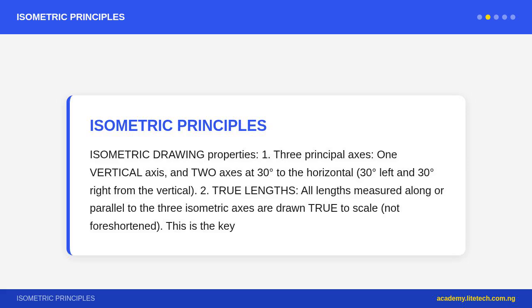Step blocks. Many WAEC questions show a rectangular block with a notch or step. Break it down into simpler boxes or use the coordinate method. 1. Draw the full bounding box. 2. Remove the sections that are cut away, draw over them with the background color or leave them out. 3. Add the step edges.